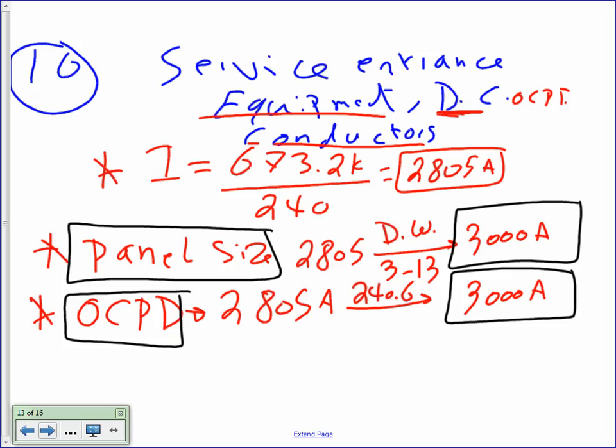This should be a 400 amp panel here. I can put a fuse or a circuit breaker ahead of it or inside it as high as 400, but not higher than 400. Does that make sense? I can put 200 amp on a panel whose bus copper inside is 400. Everybody knows that? Okay, why don't we take a 5 minute break, and I'm going to size the conductors, including the two hots and a neutral. I'm going to show you how easy it is to do the rating of the neutral all through. Okay, 5 minutes.